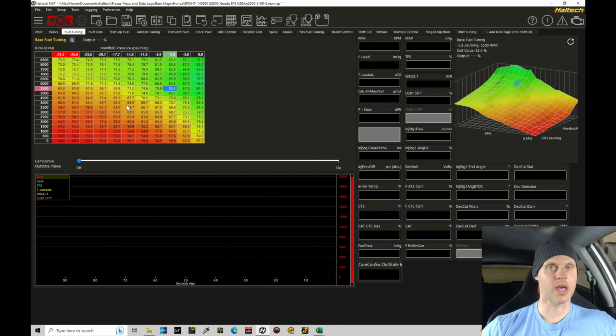Now the table here is going to be identical between low and high cam right now. We're only on low cam because we've set the VTEC to turn on at 9,000, and we're not going to hit that high of an RPM. So we've set the table here, reasonable values. We'll work with the low cam and the calibration tuning first, then we'll copy low cam into high cam and tweak and adjust that when we get to that specific tutorial. But now we've configured the table.